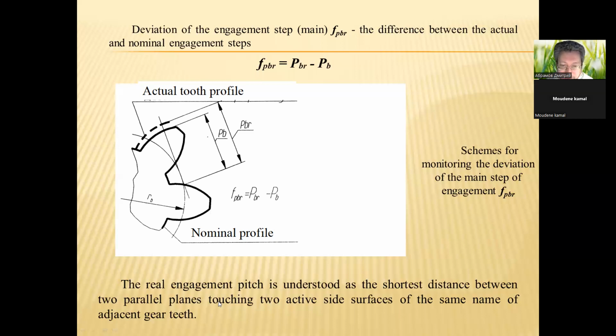The real engagement pitch is understood as the shortest distance between two parallel planes touching two active side surfaces of the same name of adjacent gear teeth.